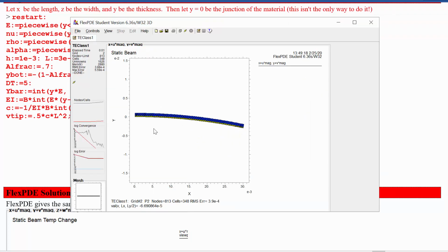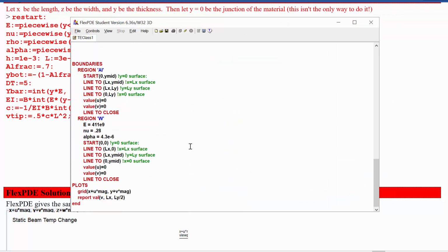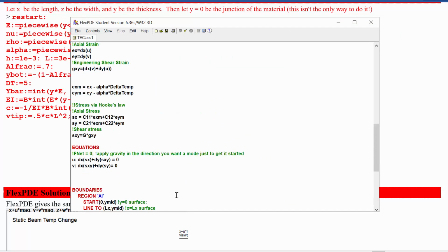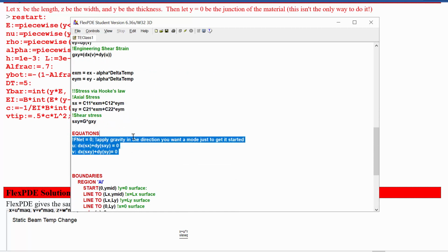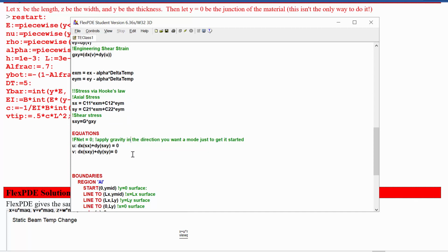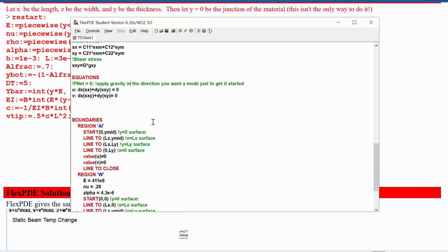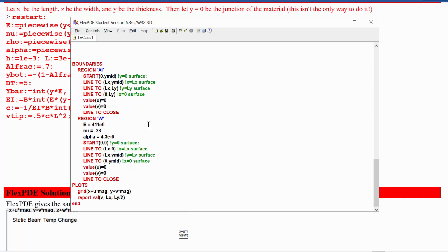Final observation is this version of going to 2 dimensions, where we've gotten rid of any coupling of the stress from that Z dimension into the X and Y, is equivalent to saying that there's no stress in the Z direction, no coupling back in, no stress there. So this is the plane stress condition. If we'd rearranged these equations a little differently, we could have worked it into the plane strain condition, which would be equivalent to saying that it can't move at all in the Z direction.